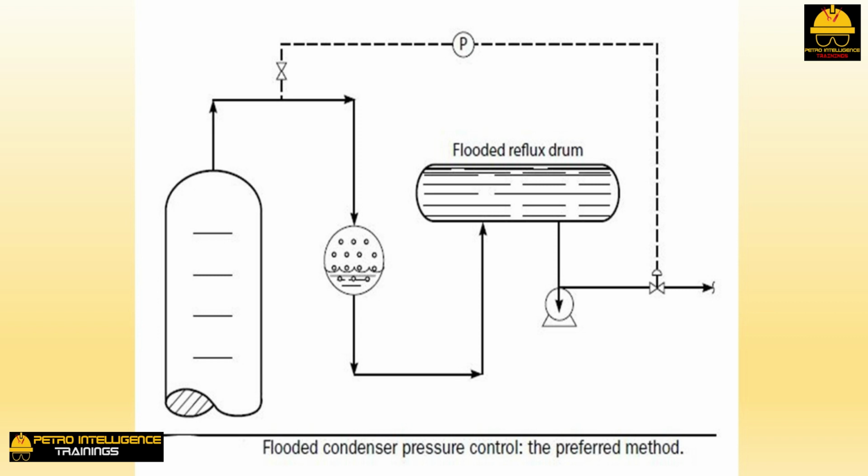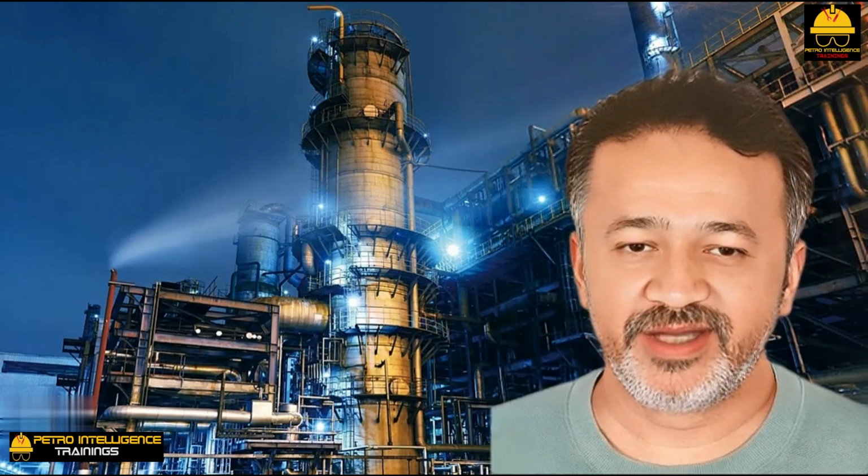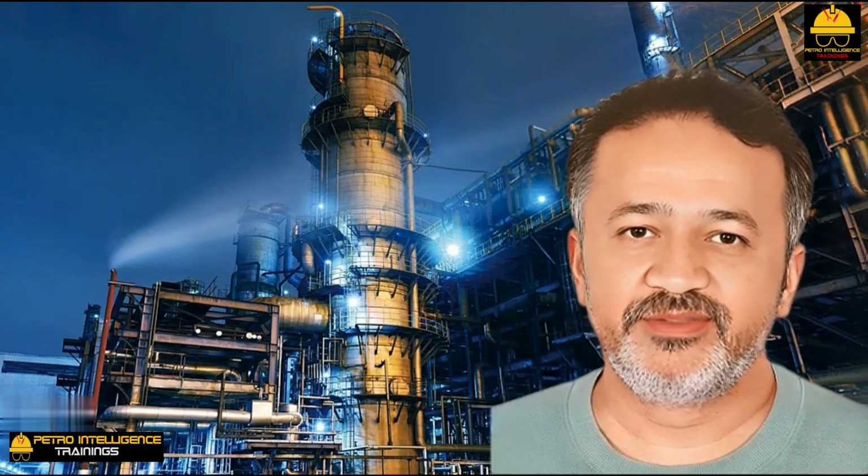Air-cooled condensers seem to work as well as shell and tube water coolers in flooded condenser pressure control service. Some air coolers are sloped toward the outlet to reduce the ratio of the delta condenser surface area to delta height change of condensate backup. I don't think this is necessary, but it may help in fine-tuning pressure control with air-cooled flooded condensers. But don't just take my word for it. Try running on flooded condenser pressure control rather than hot vapor bypass, and I think you will be quite pleased with the result.